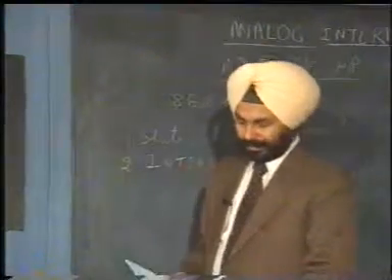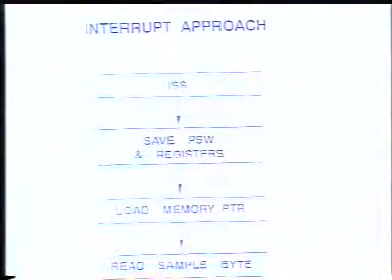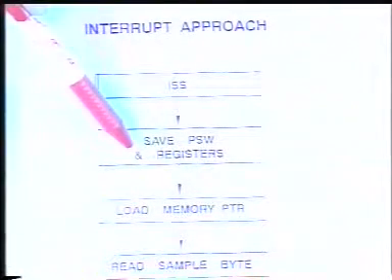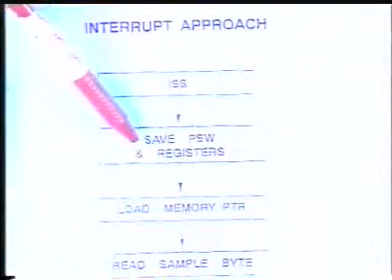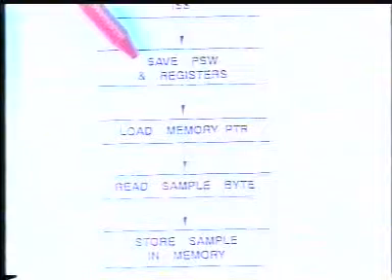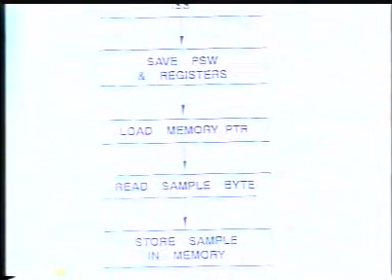In this case, the interrupt service subroutine is called, while the microprocessor was carrying on a certain job. Now it has to go back to the original job. So we have to save the status of the microprocessor. That means save its processor status and the registers, whatever are to be used in this routine.